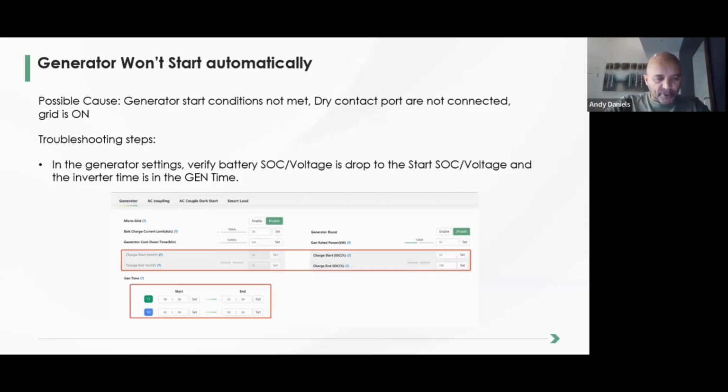Right, so here you can choose your BMS charge current limitation. This limitation is obviously to set the charge current for the generator. Remember that when a generator is running, it has to take load and charge the batteries at the same time if there's not enough PV. So you want to make sure that your loads are taken care of first and that the charging is limited so that you don't overwhelm your generator, all right?